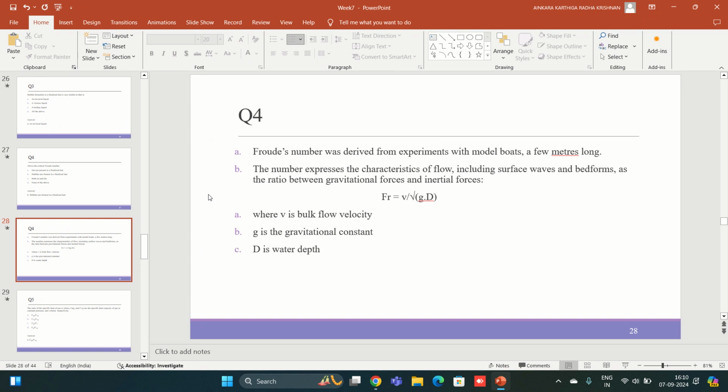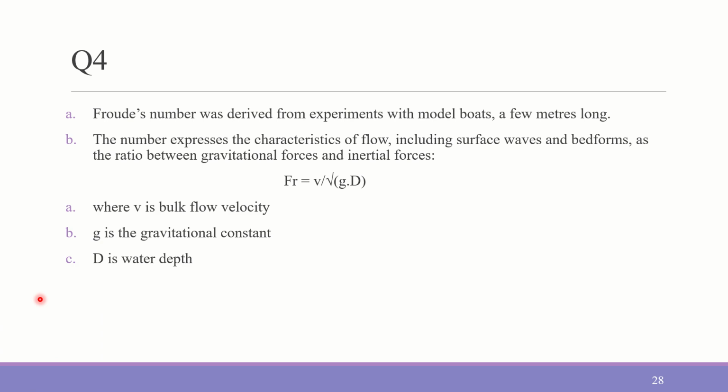So if it is above critical flow conditions, V is said to be high, and if velocity is high, we say bubble formation occurs. Therefore, if Froude's number is greater than critical Froude's number, bubble formation tends to occur inside the fluidized beds. That is this question.